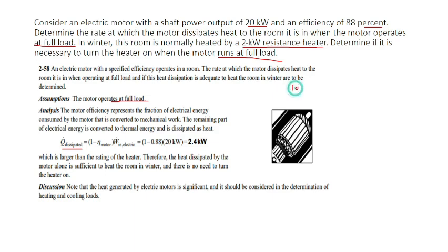If you put in 100 joule of electrical energy and the efficiency of the motor is 88%, then this electrical energy will be 88% converted into mechanical work, while 12 joule will be lost as work against friction, or lost as heat. So efficiency is 0.88. The formula is 1 minus efficiency, into the electrical input going into the system.